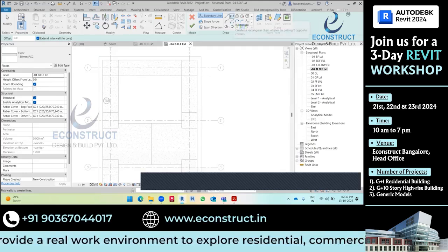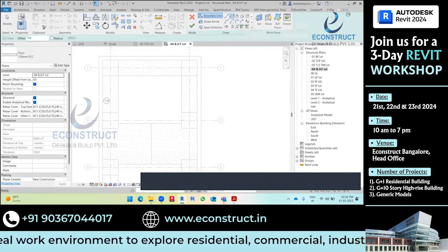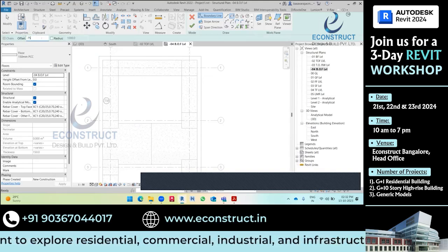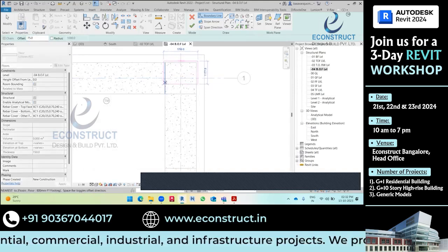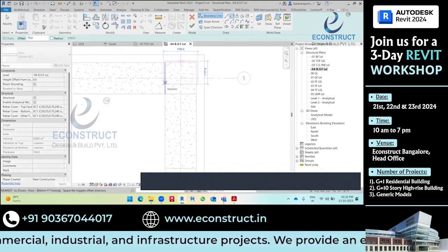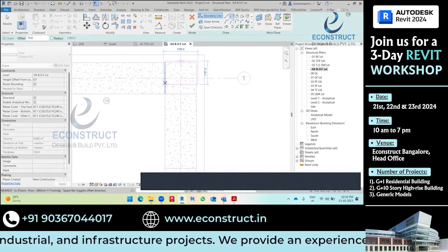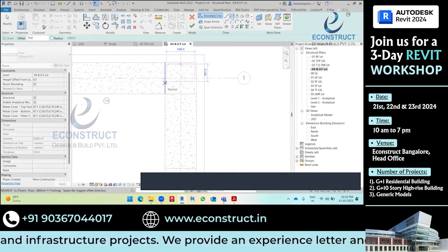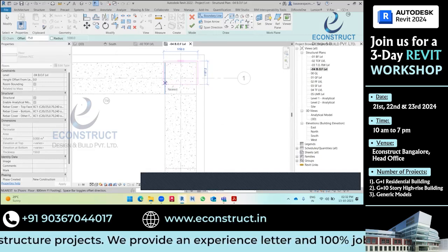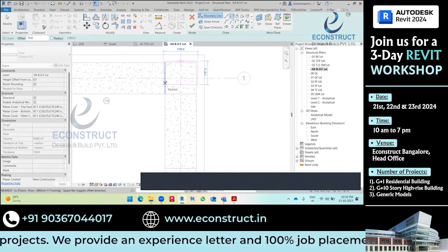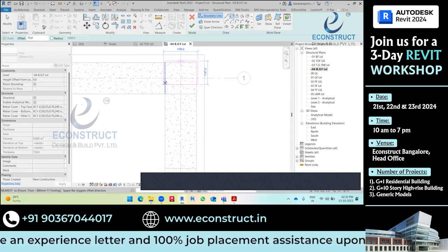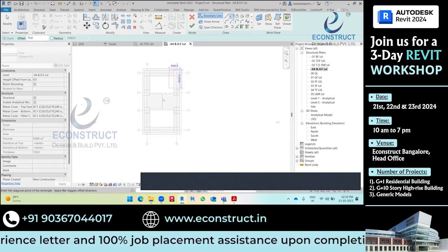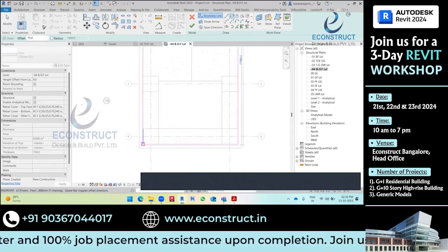Okay. So what I will do, I will take the rectangle and I will give the offset of 75 mm. Okay. So see now, if you draw the rectangle, it will take 75 mm offset. Okay. And if you press the space bar, it will come inside. If you press the space bar, it will flip. Okay. So I need 75 mm outside, right? So I am taking like this, and I will draw complete.